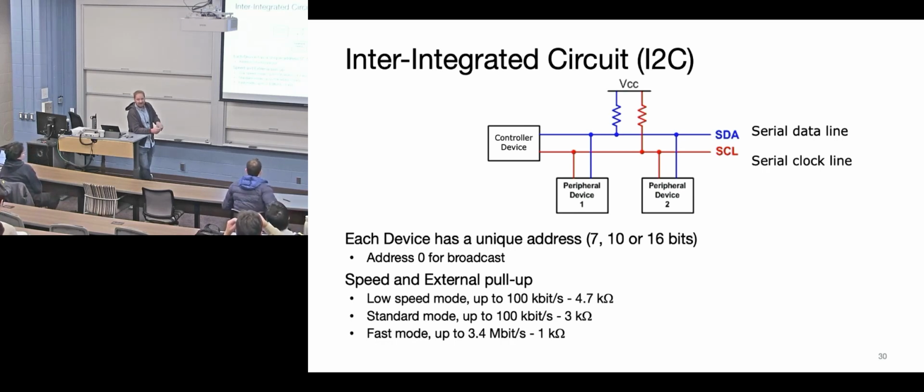There are some devices that say you can add or remove a 0 ohm resistor to reconfigure the lowest bits. So maybe the manufacturer knows that there could be an application where you put 4 of their chips on a device, to make an array on a PCB. And then they'll register 4 addresses for that IC, and then the user or manufacturer of the board is responsible for putting the resistors on there to define the last 2 bits. So that's one way to get around that.